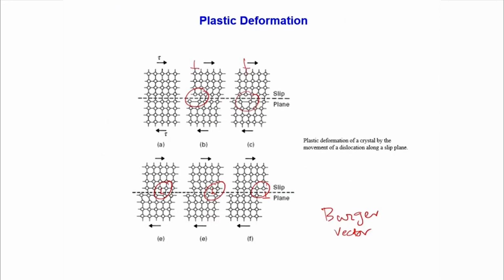Well, dislocation motion in the material happens by a small segment. That is basically known as a Burgers vector, and as the dislocation moves from one part of the crystal to the other part, it leads to a step on the surface, and that is nothing but a slip step. Okay, and remember, a dislocation can move only on a slip plane; it cannot move on any other plane. So, these slip planes are basically the closest packed planes in a material. In FCC, it is the 1-1-1 plane.